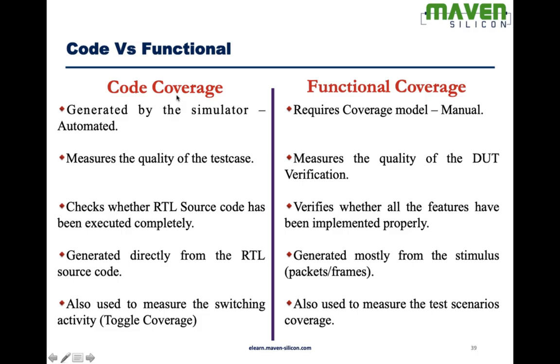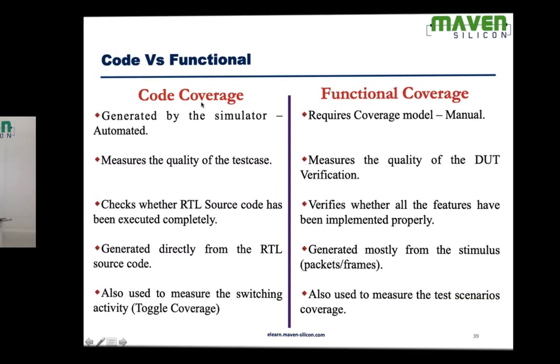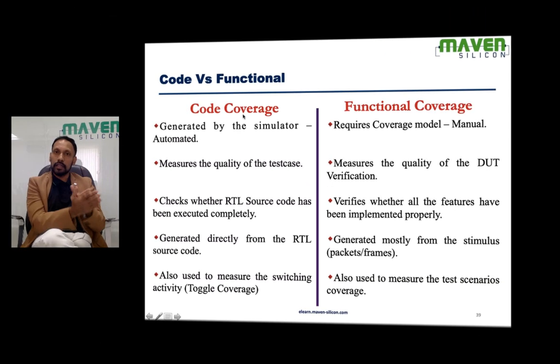And code coverage measures the quality of the test case. So with the help of code coverage, we would be able to rate the test case, whether the test case is highly productive or redundant or less productive. We can use functional coverage to measure the quality of the DUT verification, how much we have covered.